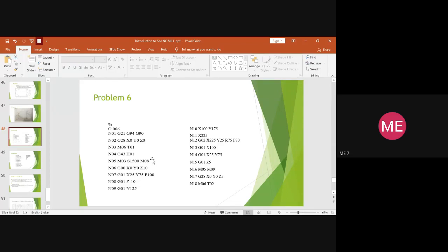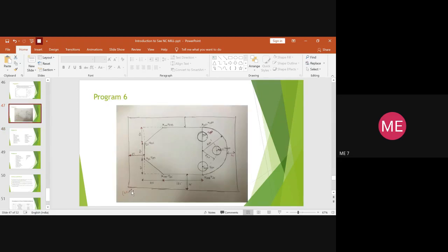Once this is done, you should bring the tool nearer to the position where you want to do the operation, right? You cannot directly go to the position where you want to give the feed rate. So first you will drop the tool nearer to the reference, automatic zero return. So it was X0, Y0, Z0. So it will be touching the blank actually.